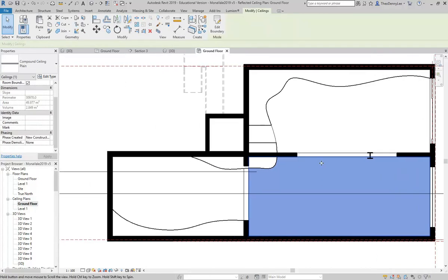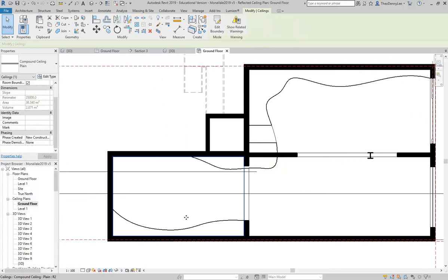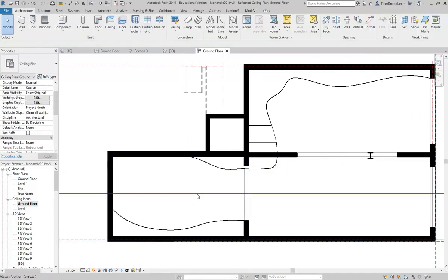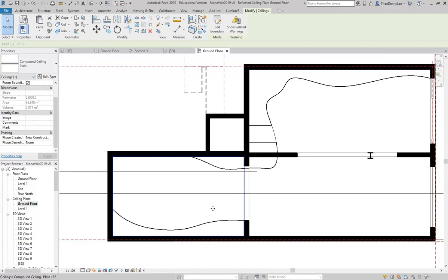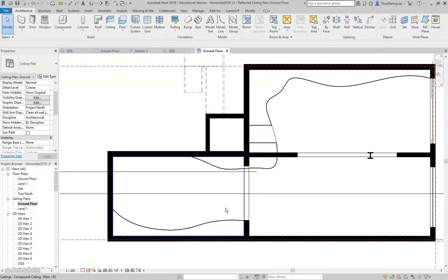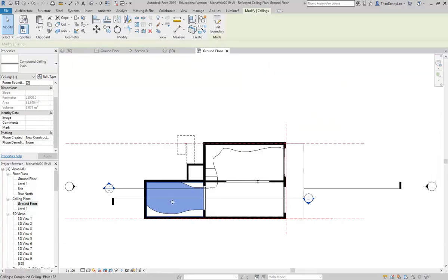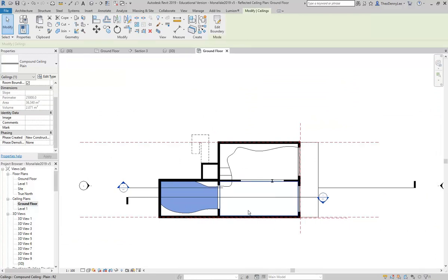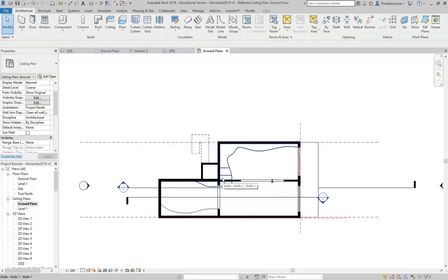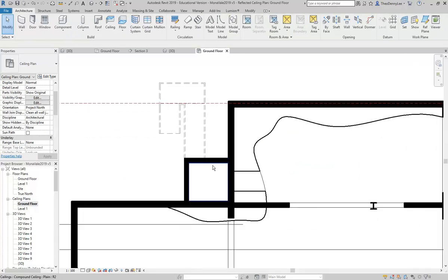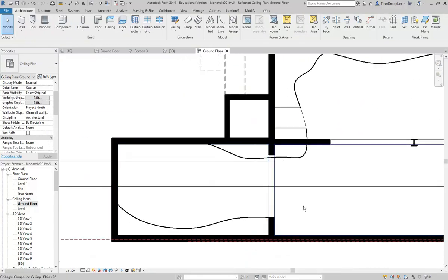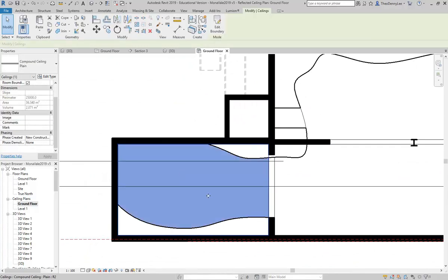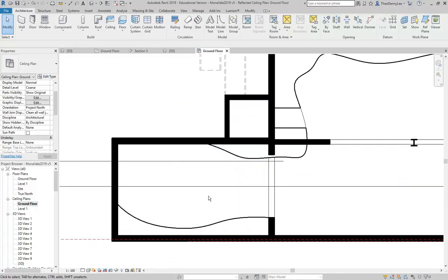So there's the ceiling, and let's see how the back, it's the same. Yes, that's right. So here it looks like there are 2 extra ceilings. I'll delete both of them, and there we are. So now we're just back to 1 ceiling. But so that you can see how to make a new ceiling, if you need to do a new one for your own design, I might delete maybe the one at the back. It's easier to make them again, so I'll just delete that.